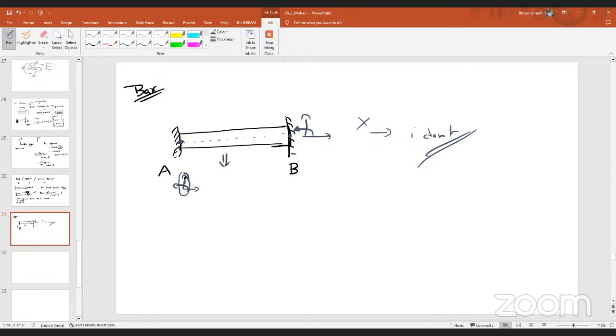So vertical in this case means shear only. How come vertical force will develop and how come moment will develop? They don't develop. So as we are dealing with the bar problem, at end A, one unknown force will be along the axial direction, FA, and another unknown force along the axial direction at B. So total how many unknown forces here? 2. If you're talking about this bar problem, I'm specifically telling you that this is a bar problem. If I don't mention that, then blindly you have to consider 3.